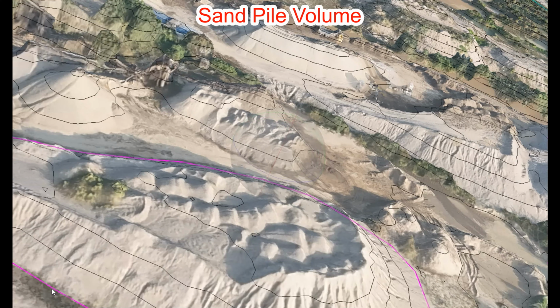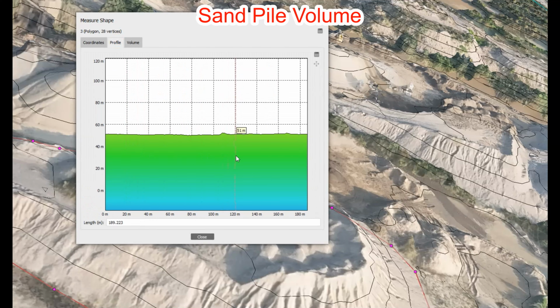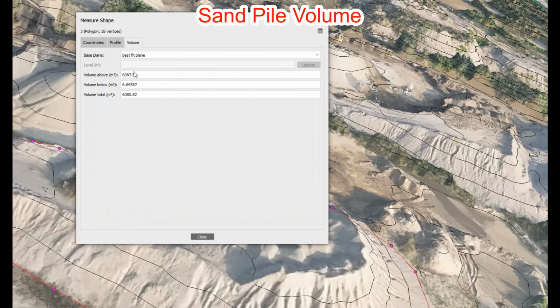Now I will again select the polyline, right click, and go to measure. And this is my profile view. It is okay. And this is my volume calculation, and the volume calculation is from the base fit plane. The volume above the polyline is 6087.51 cubic meters.